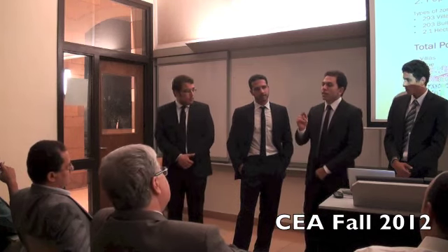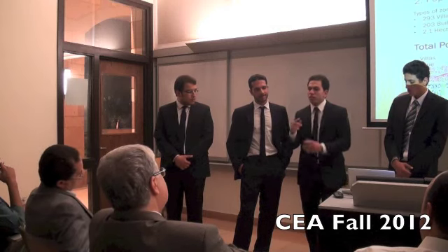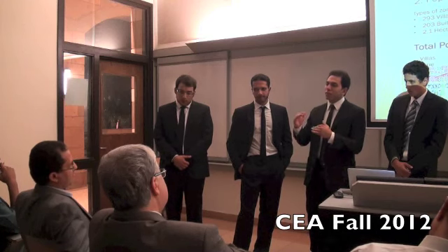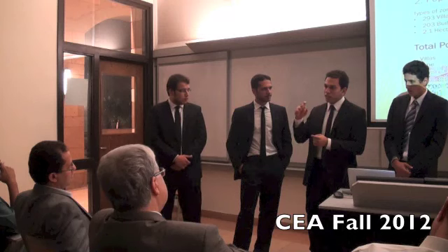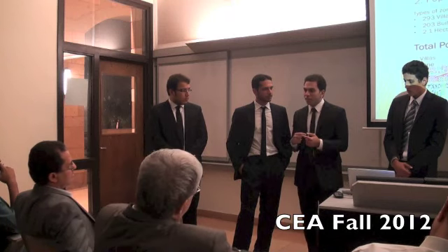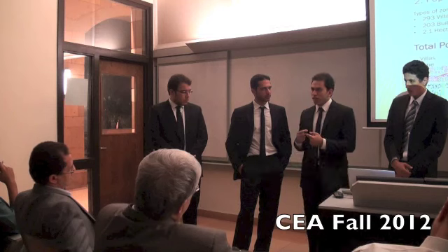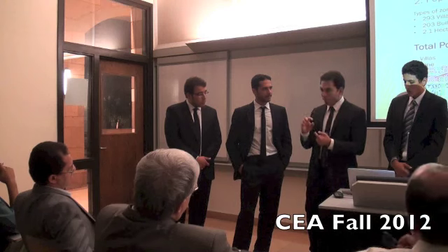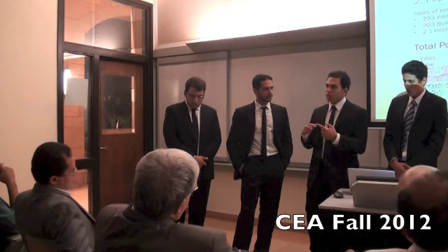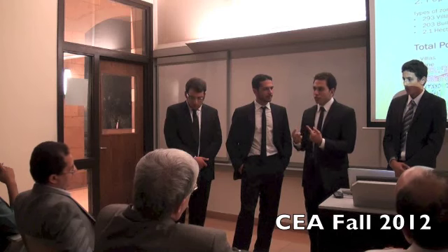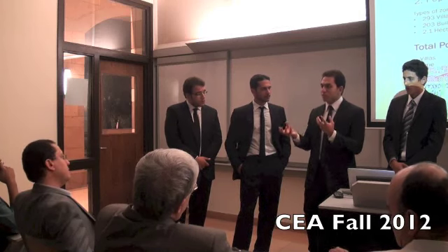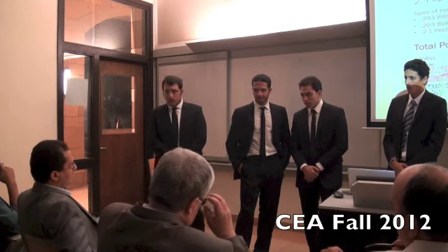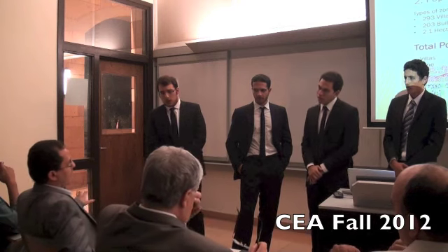I would like to add. The steady state analysis considers the maximum flow. When the flow is maximum, the pressure heads are not that high. But during the evening, when the demand decreases and the flow is minimum, the pressure loss is minimum and the pressure head is maximum. So the EPS allows us to consider Q minimum and Q maximum and the pressures in both conditions. Use the peaking factor, a maximum peaking factor, a relevant peak hour demand.